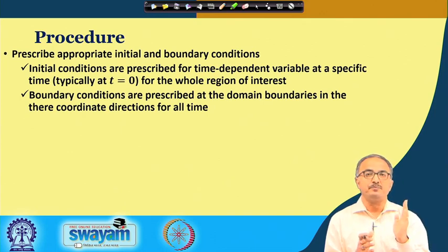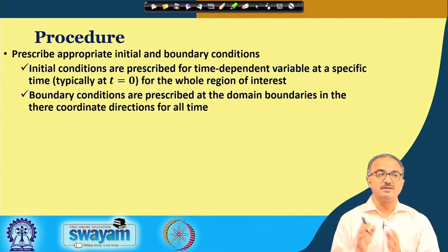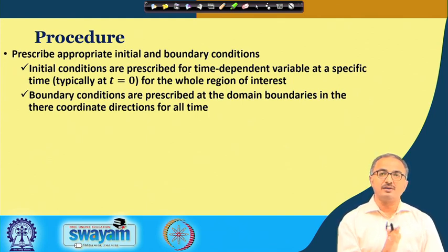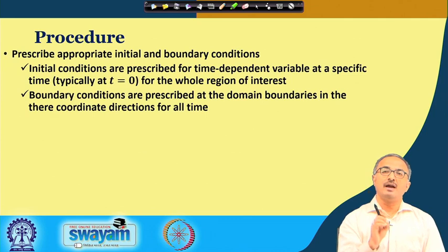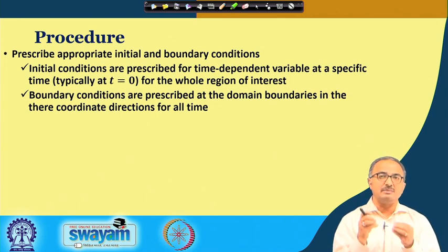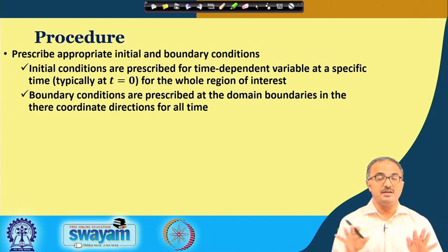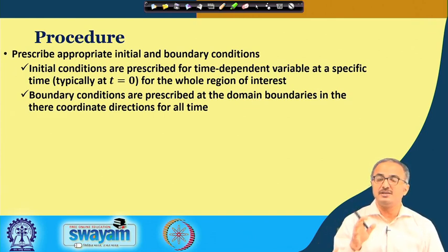Now, even though physically it is a spatial dimension, mathematically this becomes like an initial condition. Spatially it is a boundary condition, but mathematically it is like an initial condition, as if you are replacing time by x. So, you put at x equal to 0, the temperature is this. Many times the spatial coordinate mathematically behaves like a temporal coordinate, but in reality it is not. As you go along with this kind of modeling, you will find that many such situations arise.